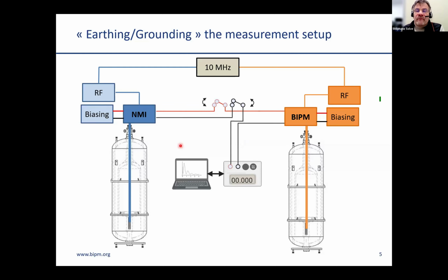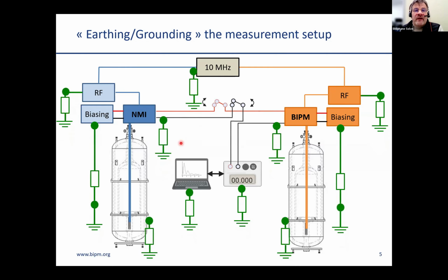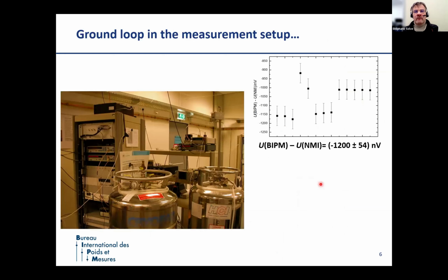But the point from this very easy measurement setup would be to, after that, really investigate all kinds of leakage resistance or existing resistance between the potential reference of the measurement setup and the one that can be reached with other parts of the equipment in the measurement setup. We want a kind of homogeneity in the measurement setup in order to avoid any leakage current, any noise, to affect the results. And we will see that right now with an example.